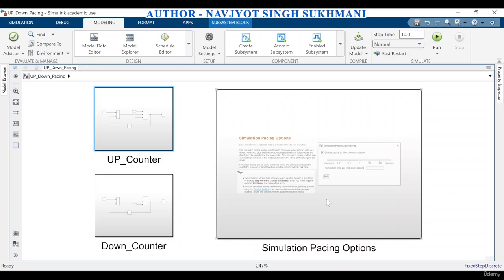In a timer, an up down counter can be utilized to create a digital timer which can count upward as a stopwatch or downward as a countdown timer. In a frequency divider, by adding certain circuit components, an up down counter can be made to function as a frequency divider, where the output frequency is a division of the input frequency.